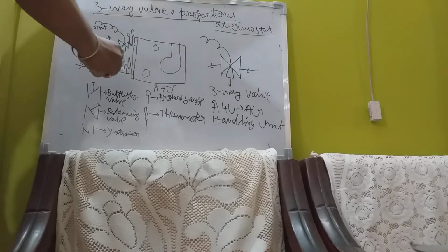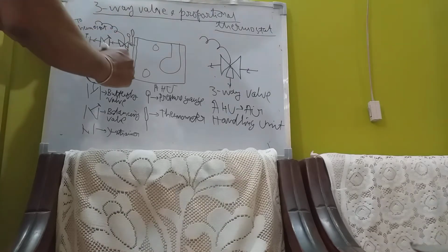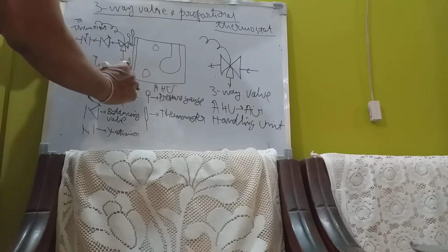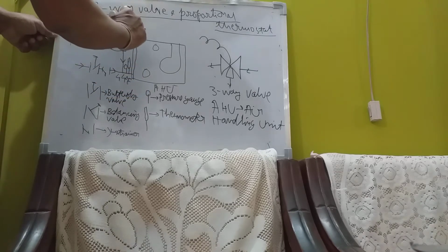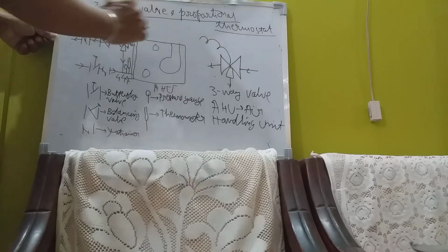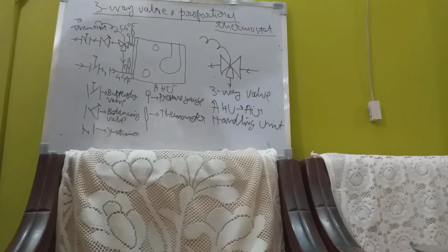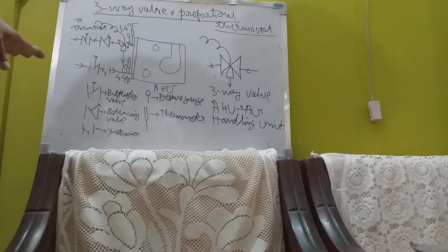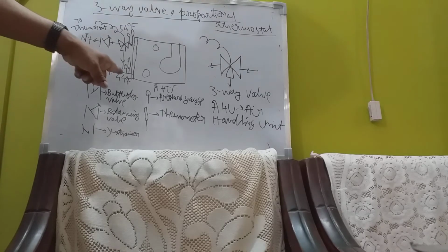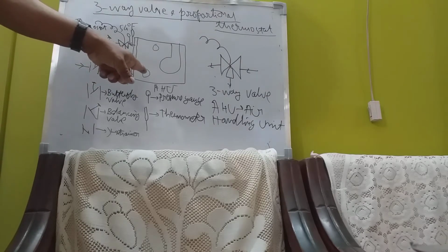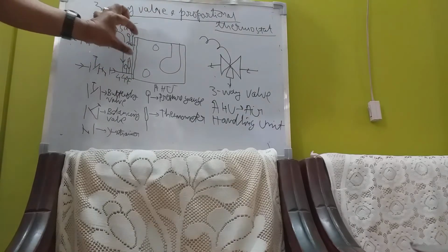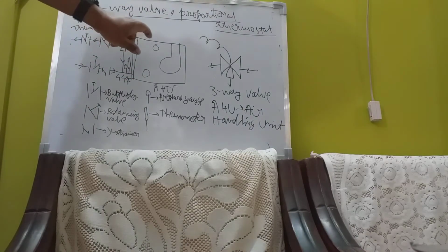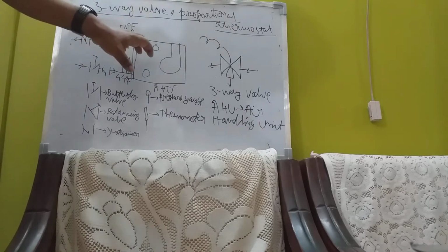Chilled water comes through this. Remember, it comes in at a temperature of 44 degrees Fahrenheit and goes out at a temperature of 54 degrees Fahrenheit. I told you during the last chilled water piping diagram that the chilling machine takes water at 54 degrees Fahrenheit and cools it down to 44 degrees Fahrenheit, and at 44 degrees Fahrenheit the chilled water is supplied to the AHU again. That means there is a delta T of 10 degrees Fahrenheit. This 10 degrees Fahrenheit determines the cooling happening in the